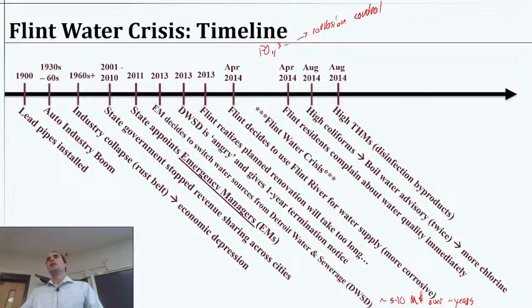And by the way, chlorine is corrosive, right? So they're increasing the corrosivity of their water, potentially. And then with this excess chlorine, they're getting lots of disinfection byproducts. So now they're ping-ponging between not disinfecting enough and creating disinfection byproducts because they disinfected with too much chlorine. They're having a real bad time because their plant is not designed properly.